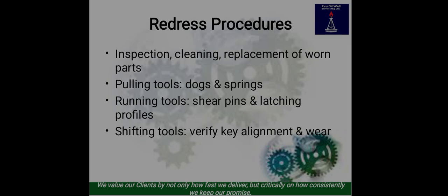Steps include disassemble the tool, clean thoroughly, inspect for wear, tear, and damage, replace worn-out parts such as dogs, springs, shear pins, seals, reassemble and test function correctly. Redress is compulsory. It ensures tools don't fail downhole.